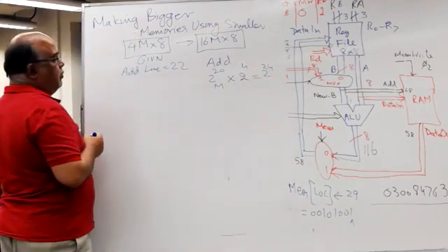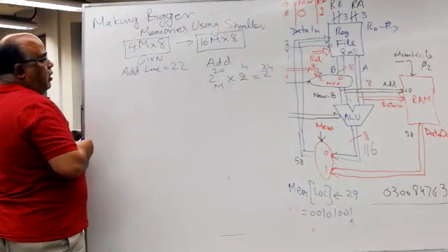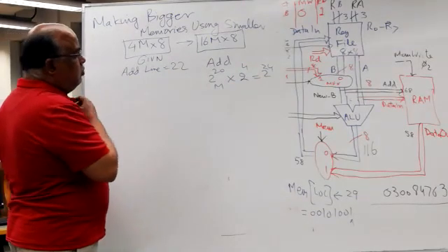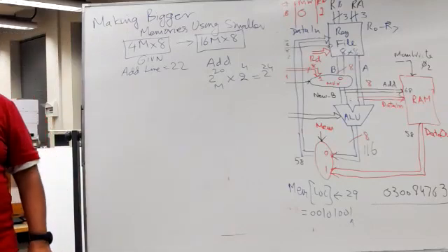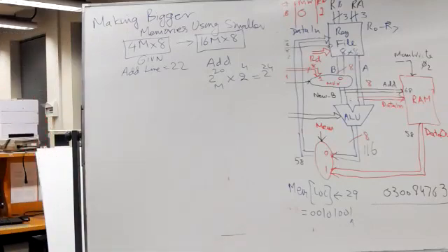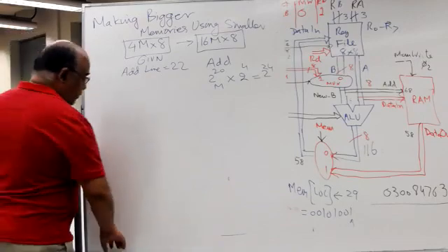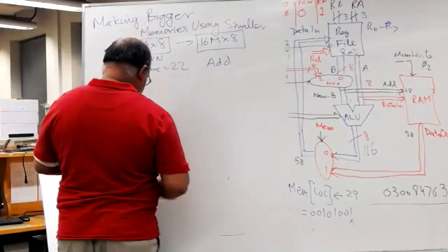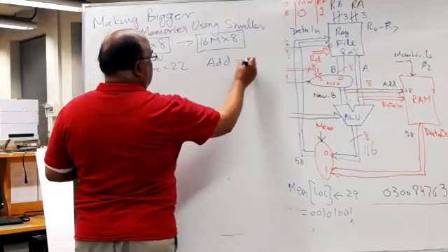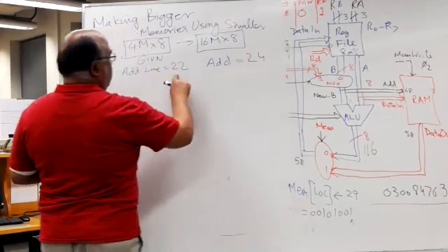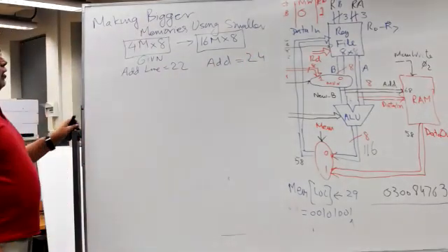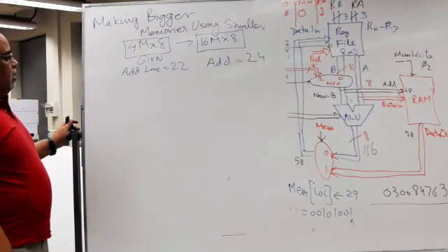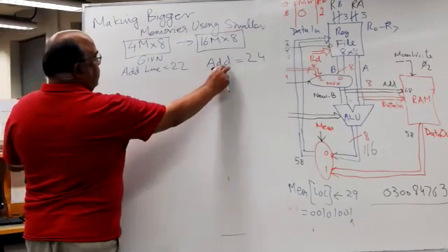So 16 megabyte memory actually has 16 million locations. So it needs 2 raised power 24 total memory locations. So for this, you have an address line size of 24. So you can see there are two extra address lines that we will use to make our vertical expansion.